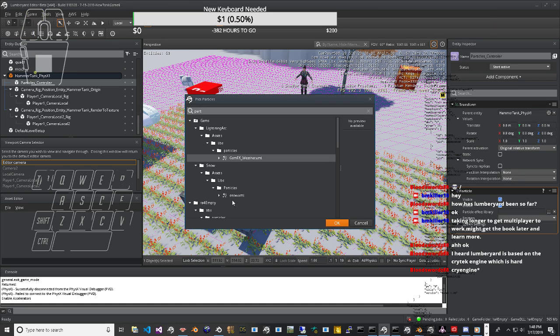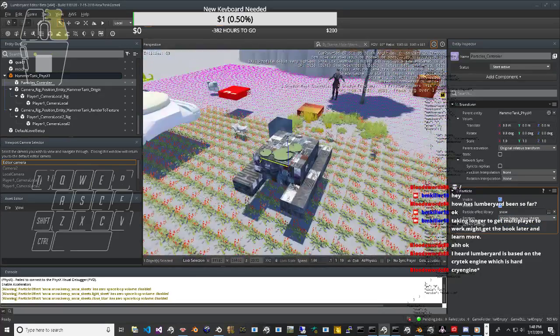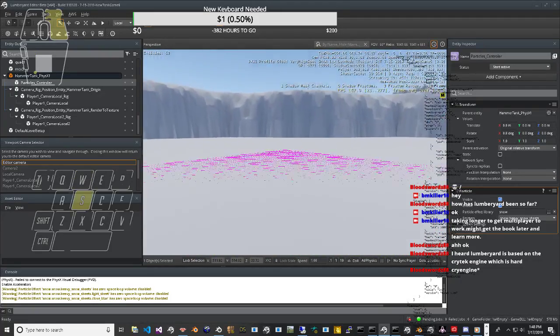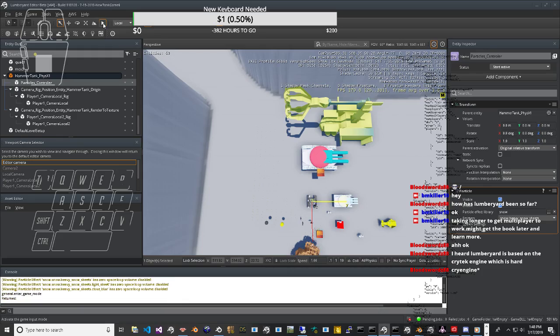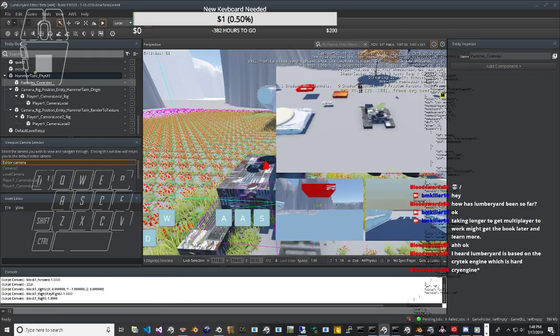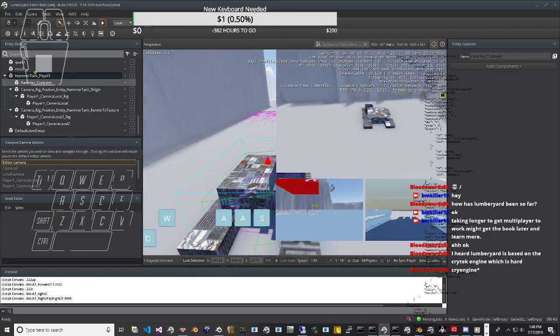Next is D = μp Fz, which is a factor with the form of the Newtonian model, normal force times coefficient of friction. In our sample, A1 is 0, so μp acts exactly like a Newtonian friction coefficient. In all cases, we should expect A1 Fz to be much smaller than A2 so that it will be, at most, a small correction to the Newtonian behavior.